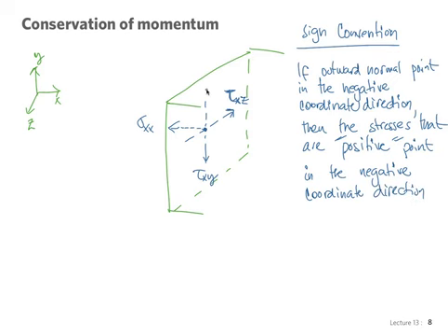So this is what we drew before, the positive face, if you will, and now we've drawn the negative face, and we've always pictured the stresses in what would be considered the positive direction. So now we're going to be able to use all of these conventions to do a complete force balance on an infinitesimal cube of fluid. And we can call each face what it needs to be, and so on. Every single stress can be considered.